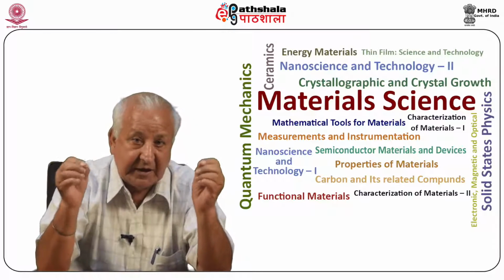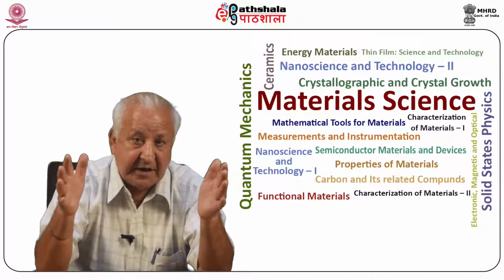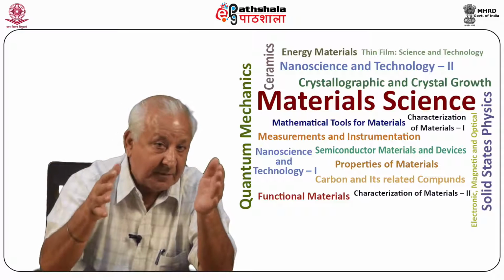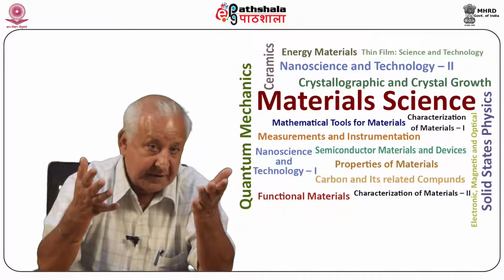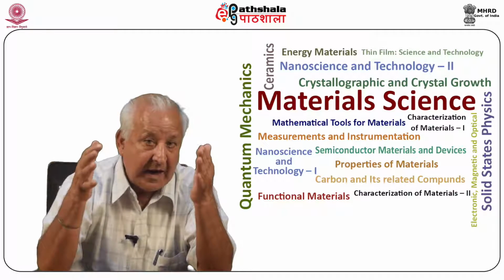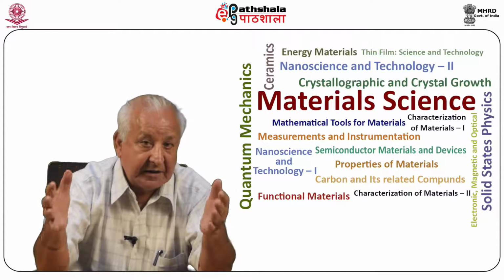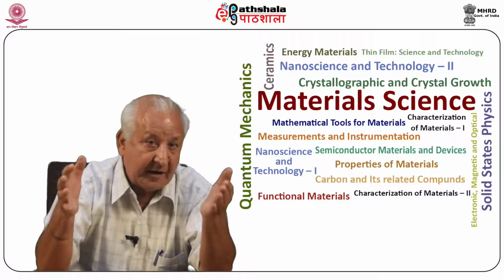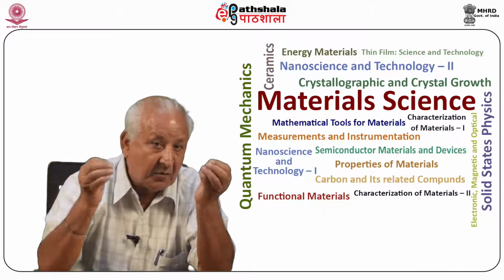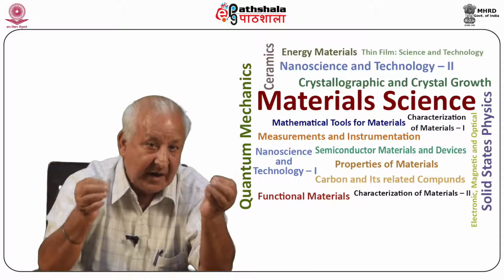The furnace used here consists of two halves, the lower half and the upper half. The temperature maintained at the lower half is just below the melting point of fluorite, and the temperature of the upper half is above the melting point of fluorite. The crucible is made of platinum and has a pointed lower end, as shown in the diagram. The crucible is filled with high quality natural fluorite or purified powder if required, to which desired impurities may also be added. A platinum wire hangs the crucible in the upper furnace until the contents are completely melted.